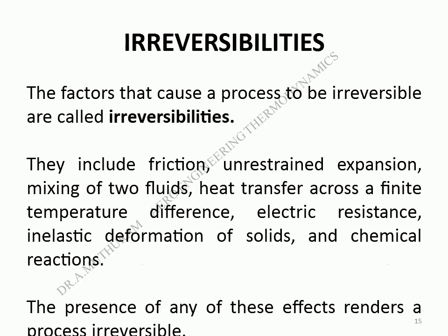Irreversibilities. The factors that cause a process to be irreversible are called irreversibilities. They include friction, unrestrained expansion, mixing of two fluids, heat transfer across a finite temperature difference, electric resistance, inelastic deformation of solids, and chemical reactions. The presence of any of these effects renders a process irreversible.